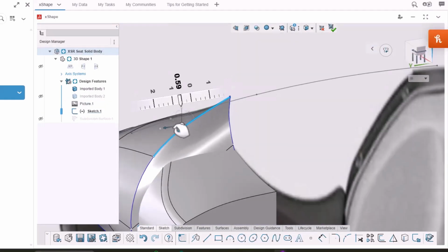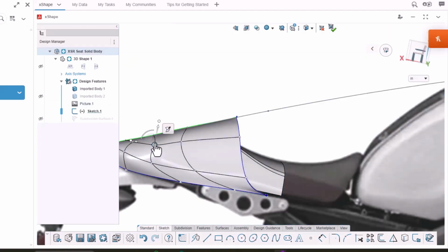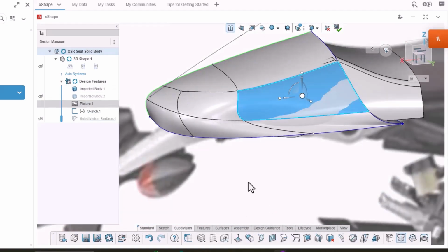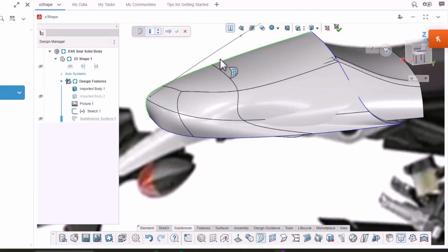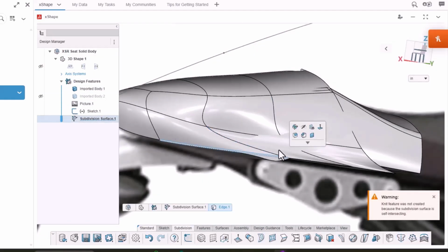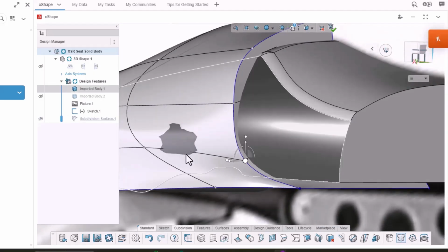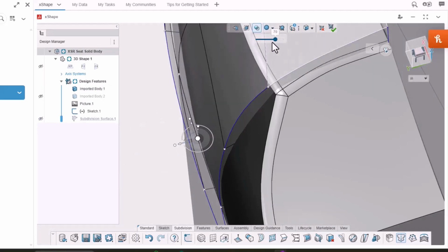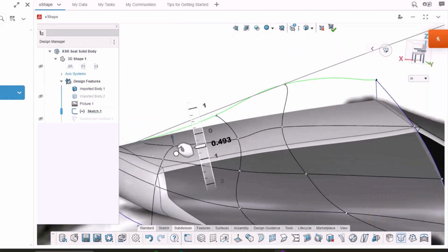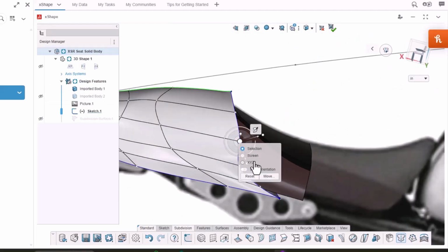And I ended up playing around with that for quite a while, just trying different curves and shapes. And at this point, I decided I needed another adjustment area. So I added an edge loop just to give me a bit more control. So that's kind of what that process looks like. And then further on, I could see that my cowl wasn't formed around the seat very well. So I made it transparent just to get those areas formed out a bit better. And then I kept working on things.